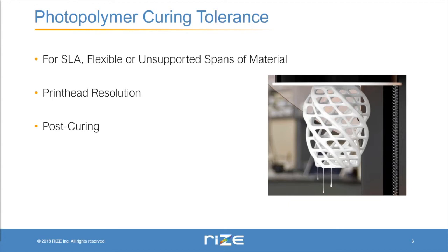So that's something, if you do plan on using photopolymer curing, you'll have to pay attention to, making sure that if you want parts to last for a long duration, you'll have to keep them in an environment where they're protected from those heat and chemical effects.